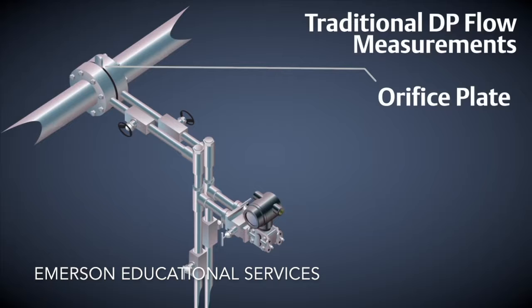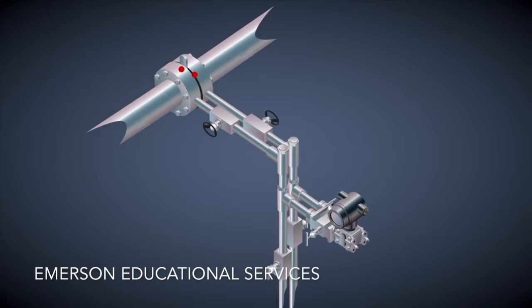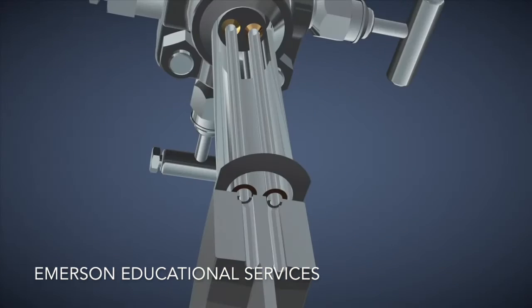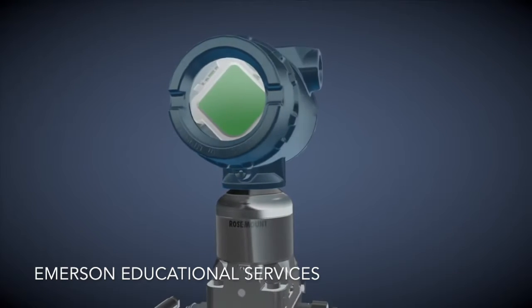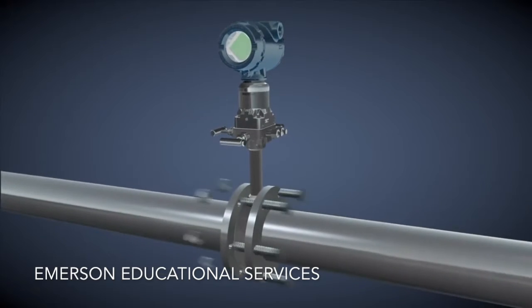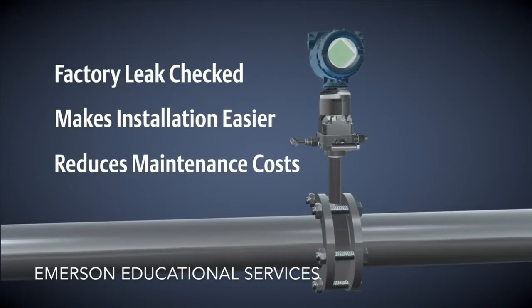Traditionally, transmitters were connected to the process with external impulse piping. Impulse piping is a major expense and gives opportunities for multiple leaks and creates unnecessary safety hazards by adding extra valves and manifolds to the process connection. Now, with new and improved primary elements, the impulse piping is built into the primary element. This allows the transmitter to be directly mounted to the isolate and equalize valves, resulting in an integrated flow meter. The built-in piping is factory leak checked, makes installation easier, and reduces maintenance costs.